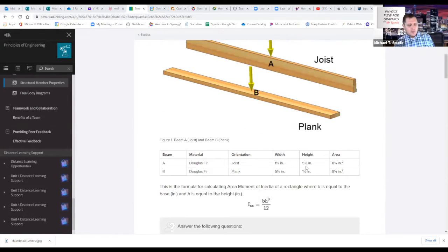What we need to do first is understand how to calculate the moment of inertia. And here it is right there. There is our calculation for the moment of inertia. Now this letter XX is just going to say the point along this line. So if you draw an imaginary line, you're looking at a cross section. Remember we already did this with centroids, right? We did the cross section. Now we're going to do this as well. We're going to look at the cross section of this beam and figure out what the moment of inertia is.